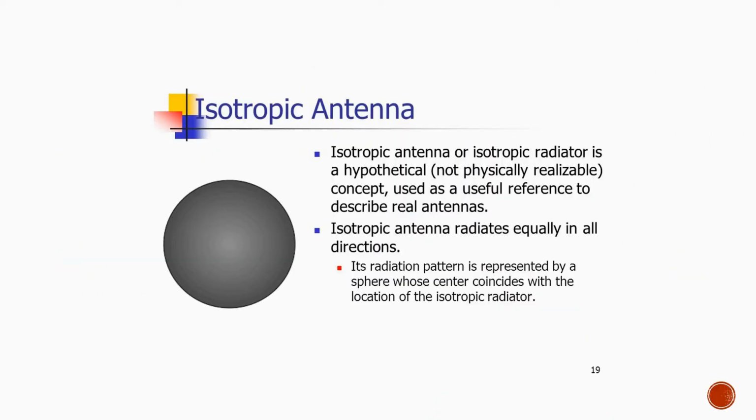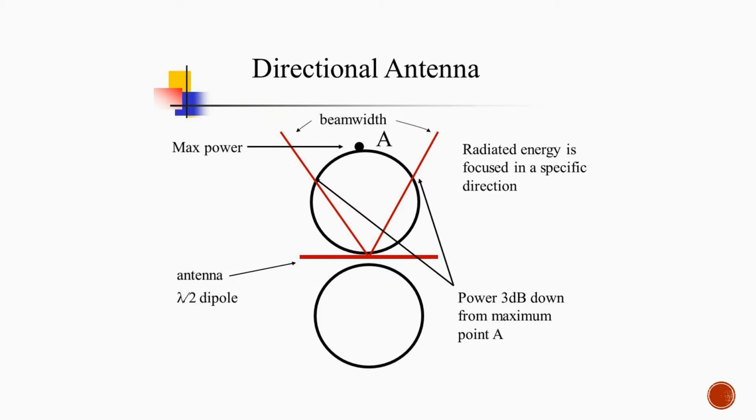The third point I'm going to say is the antenna. From previously 2G, 3G or 4G, we are using isotropic antenna. Isotropic antenna is actually the signal will send equally to all directions. So means it's useful if you use multiple applications, but now we only have used 2 applications for maximum. This kind of transmission will require more transmission power than directional antenna. In 5G, we're using directional antenna, which the signal will be focused in specific direction. We could save about at least half of transmission power than using isotropic antenna.